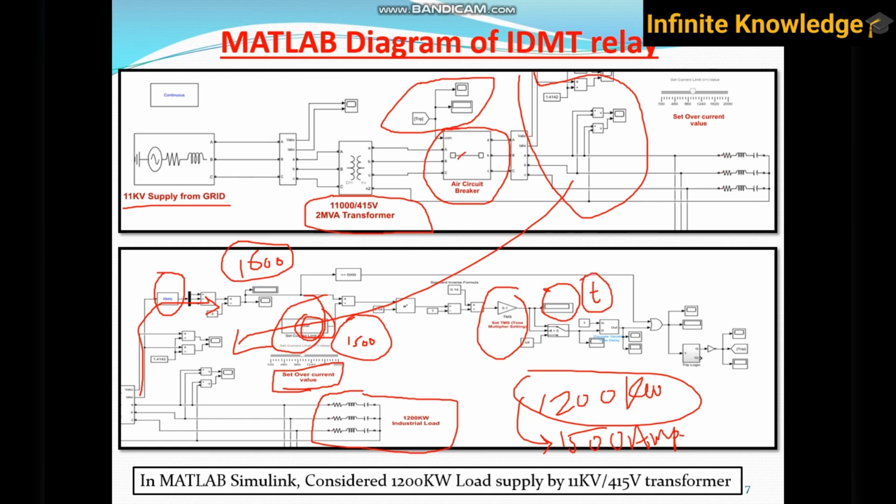So this breaker will get off and isolate the faulty part from the circuit, and save it from further consequences. Okay, and here is the short circuit protection also, which is 5 times. If my current is suddenly high due to any type of fault like LG fault or triple LG fault, then within some microseconds my breaker will get isolated. So there are two protections covered in the MATLAB simulation, overcurrent as well as short circuit. We will check all the things in brief in the MATLAB simulation.